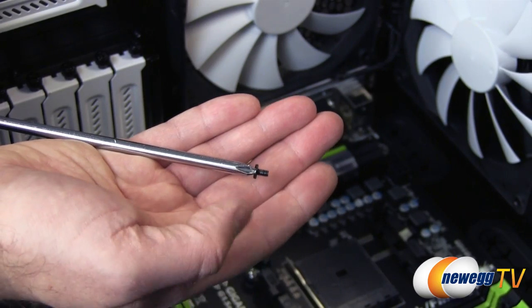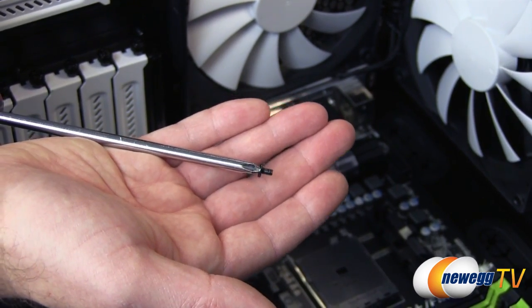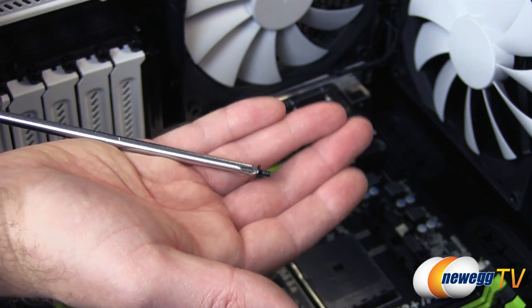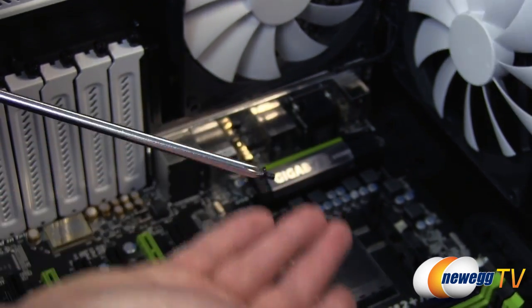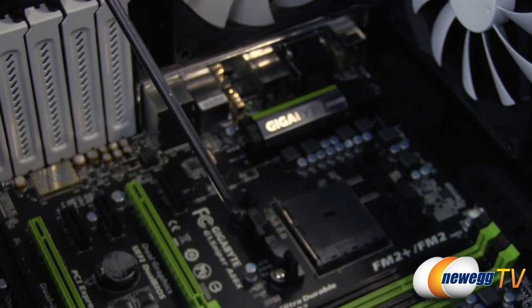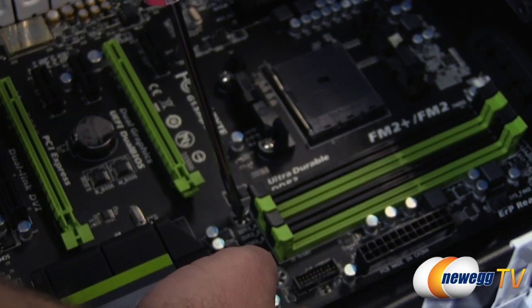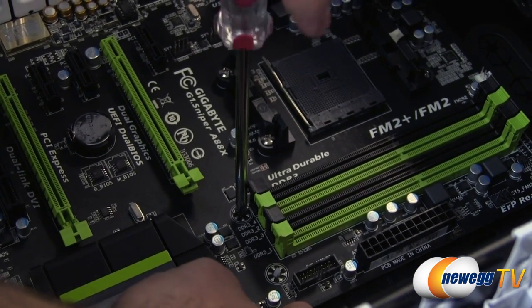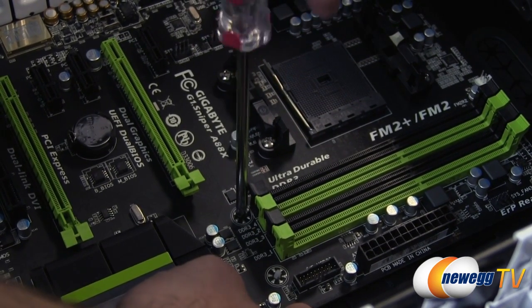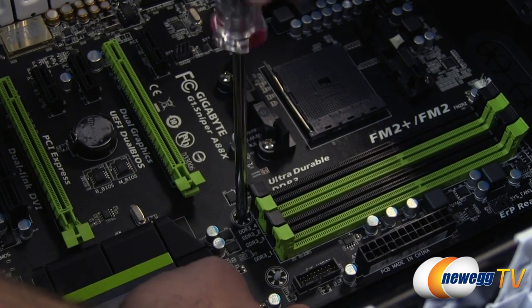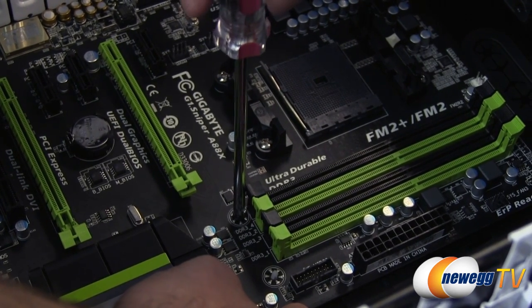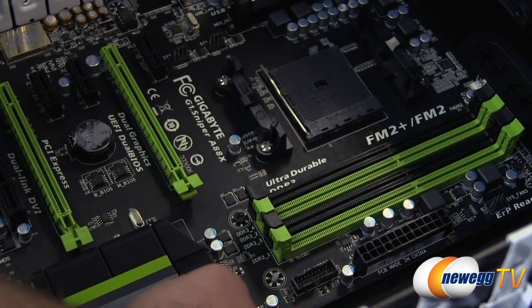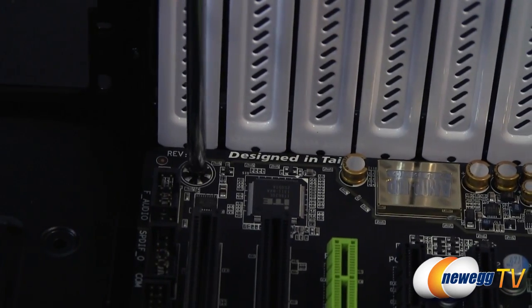So I'm going to go ahead and use my magnetized screwdriver here, which is perfectly safe. Don't worry about magnetized screwdrivers. They're not magnetized enough to do any damage to the motherboard, but that will allow me to really get that lined up there and drop it down in. And then I'm just going to go ahead and get it just barely snug on there before I add screws to some of the opposite corners. And I'm starting with kind of a central mounting point right here for starters. And there is our last screw.